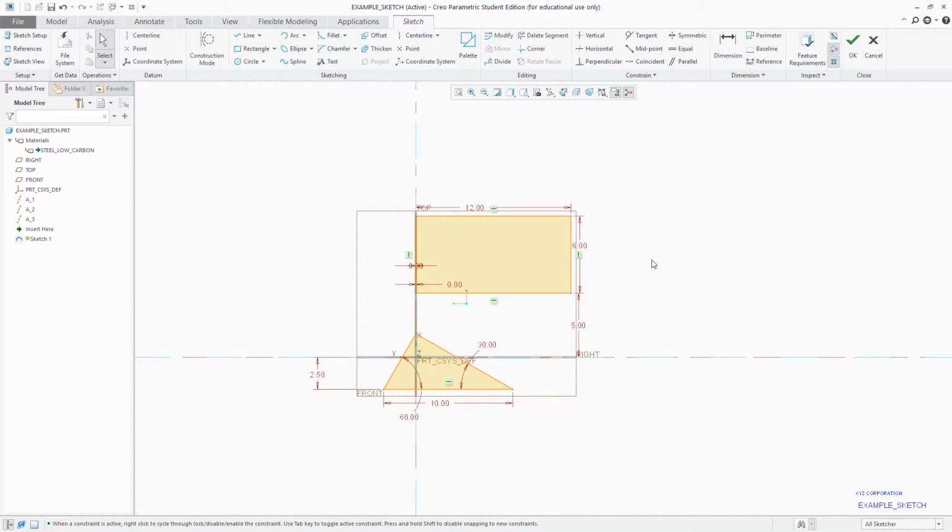On the contrary, when you try to select the entities from right side to left, now you will see the box that we form is not of continuous solid line. Instead it is a kind of dash line, and whichever entity it touches, all those entities get selected. Like this, you can see 3 entities got selected.